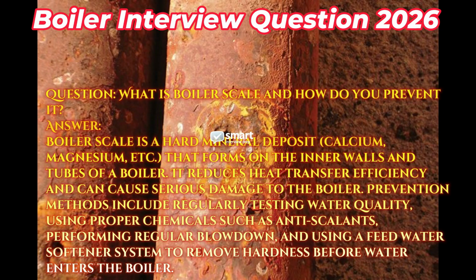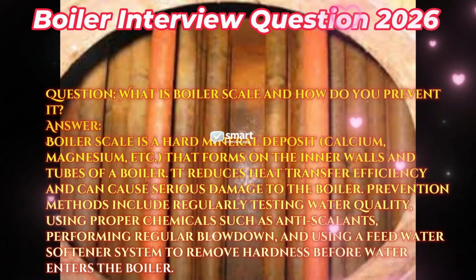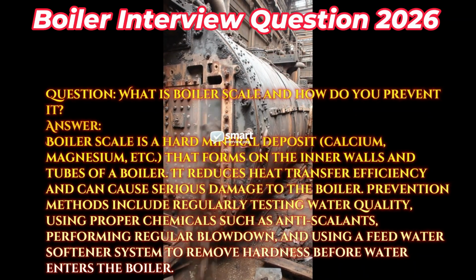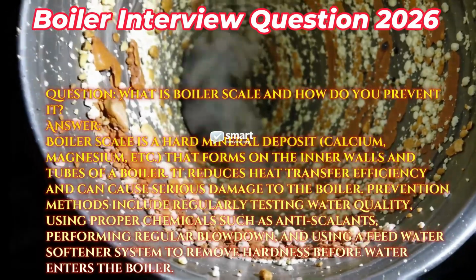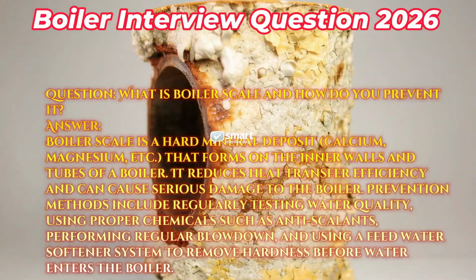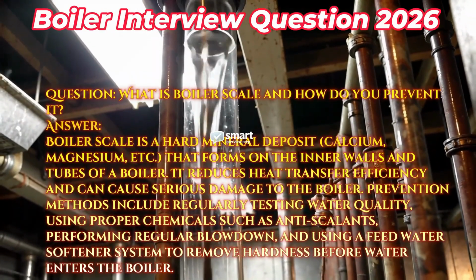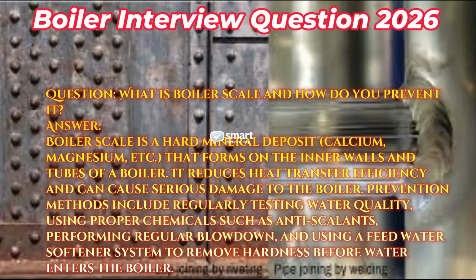Question: what is boiler scale and how do you prevent it? Answer: boiler scale is a hard mineral deposit, calcium, magnesium, etc., that forms on the inner walls and tubes of a boiler. It reduces heat transfer efficiency and can cause serious damage to the boiler. Prevention methods include regularly testing water quality, using proper chemicals such as anti-scalants, performing regular blowdown, and using a feed water softener system to remove hardness before water enters the boiler.